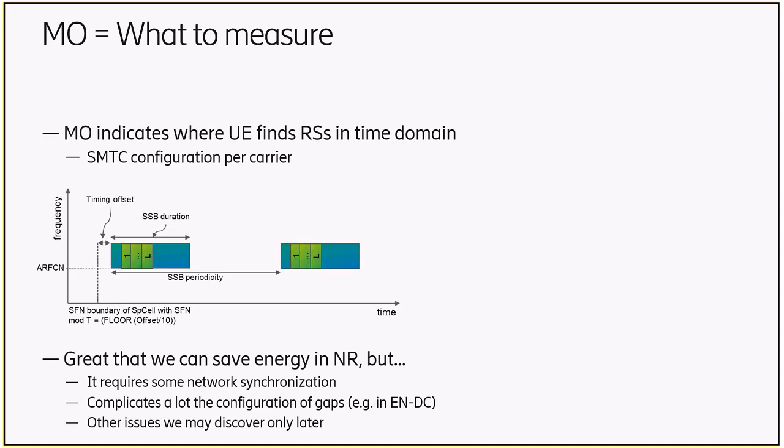No. Those are periodical, well defined. Yeah, he was talking about showing the figure, the shifts between the SSBs. I didn't explain in detail, but there is this concept of SSBs and SSB bursts. So basically, simplified, a burst is all those beams that could be transmitted within that packed window, and for each beam this is also periodic.